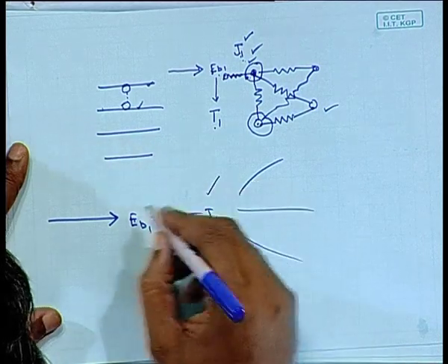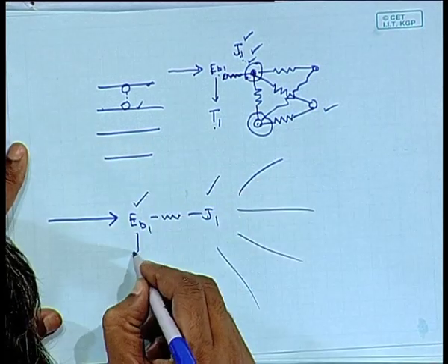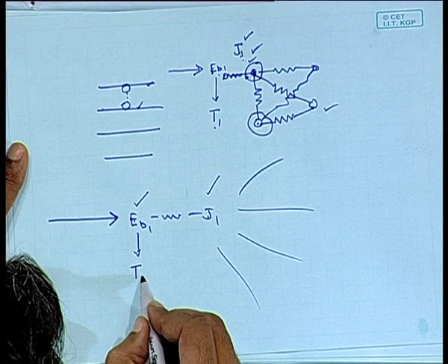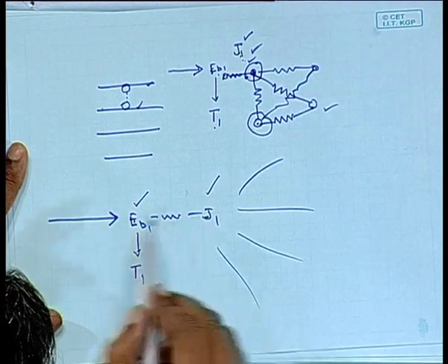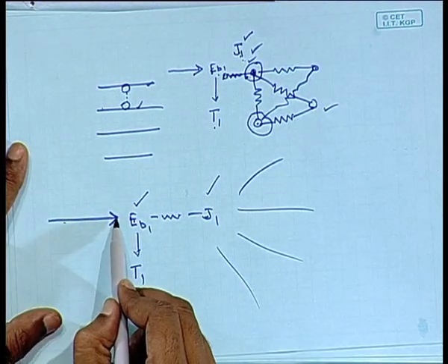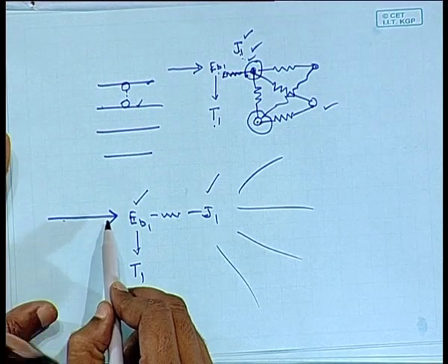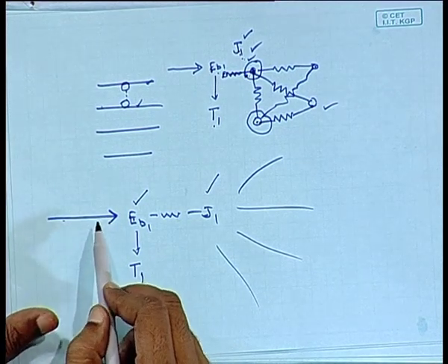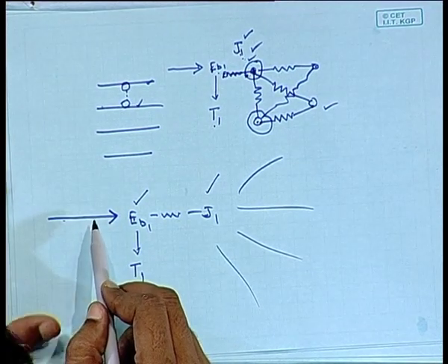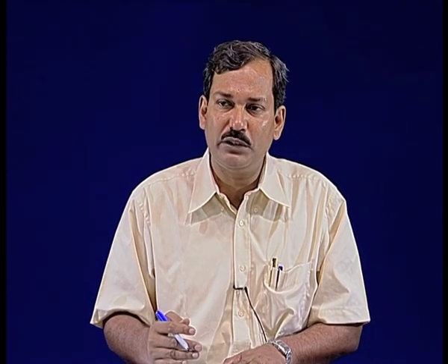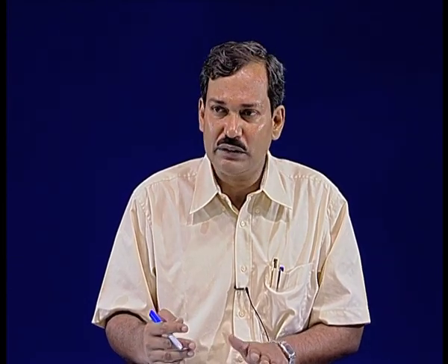Knowing this, I can calculate T1, and with these two I can find the amount of heat to be added or extracted from the surface to maintain its temperature at a constant value. So the network method is just the initial part for radiation exchange problems. Any complex problem involving more than 3 surfaces has to be solved by the matrix inversion method.